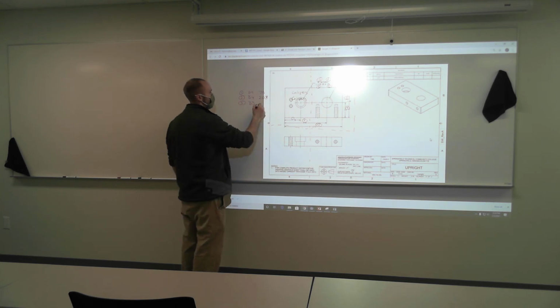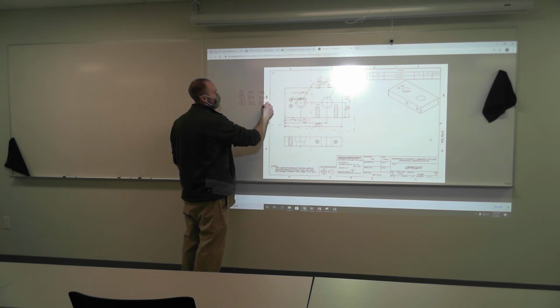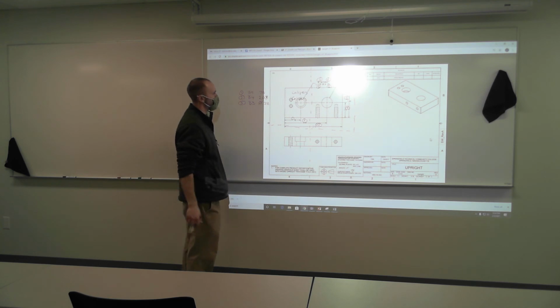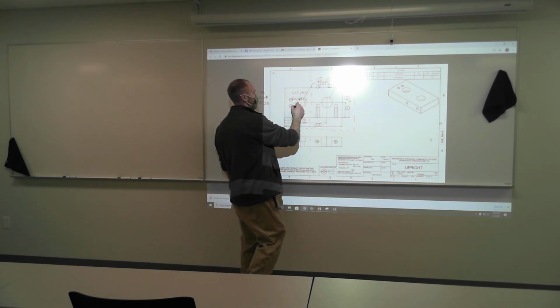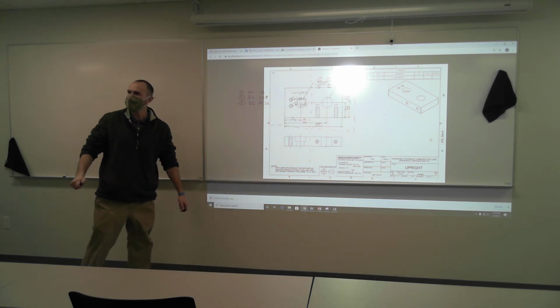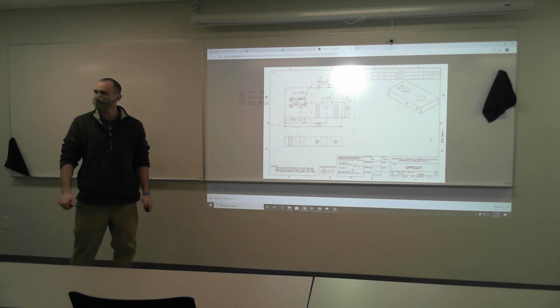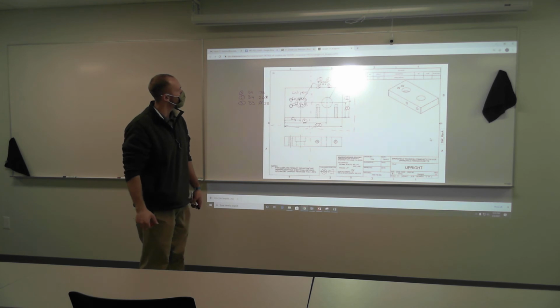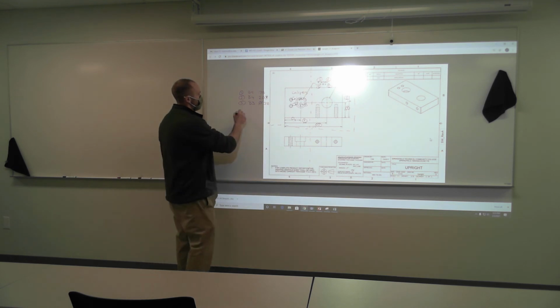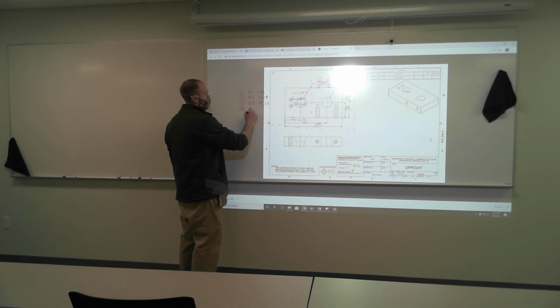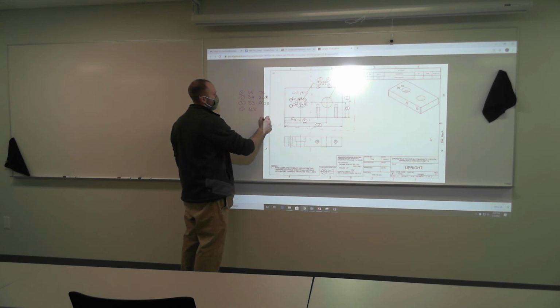B3. Characteristic is diameter 380. That is plus or minus 10 as well. What do we use to check that? You could use a pin as well. Either way, it's good. All right, so with this through condition, characteristic number 4, that is also in zone B3.